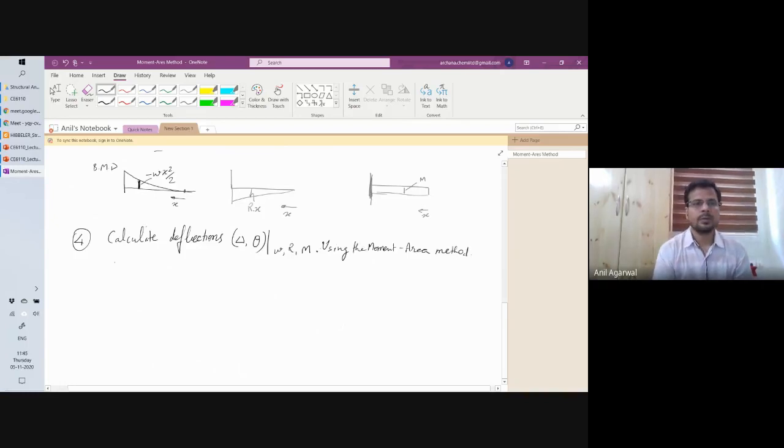The moment area. Okay. So for now, I need to know what will be the rotation and deflection at this point. All the restraints are applied here only, at this location. So I need to calculate theta and delta at that location only, at this free end. If I draw the deformed shape of this beam, which is loaded with W, this was the undeformed shape, then it deforms and develops a theta here. That theta is basically, if I draw the tangent at the fixed support and the tangent here, the same theta as the rotation at the free end.